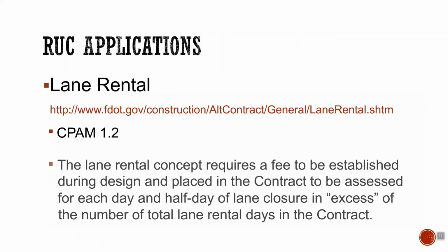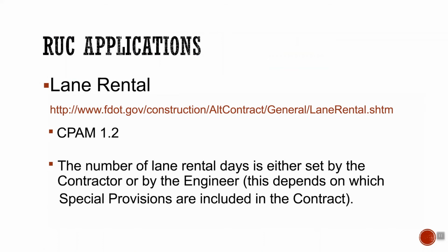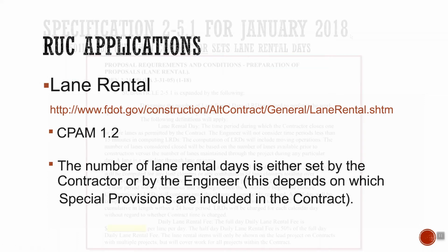The lane rental concept requires a fee to be established during design and placed in the contract to be assessed for each day or half day of lane closure in excess of the number of total lane rental days in the contract. The number of lane rental days is either set by the contractor or the engineer, and it just depends on which spec was chosen for that particular contract.